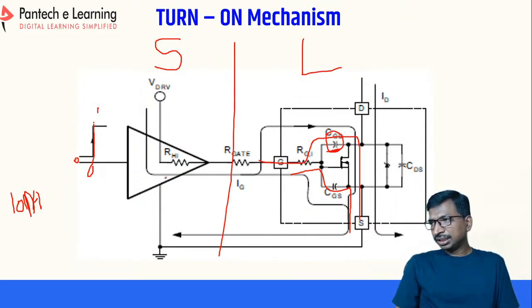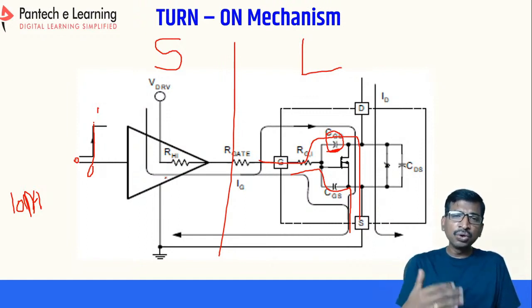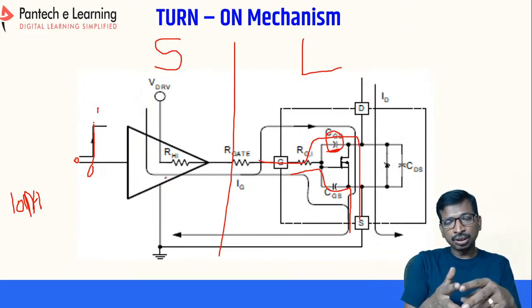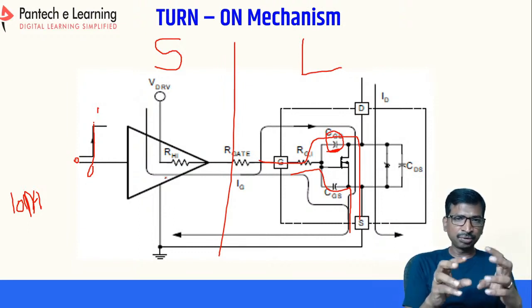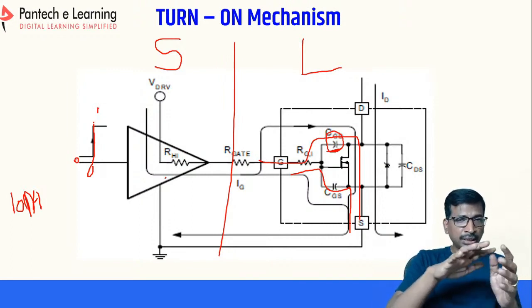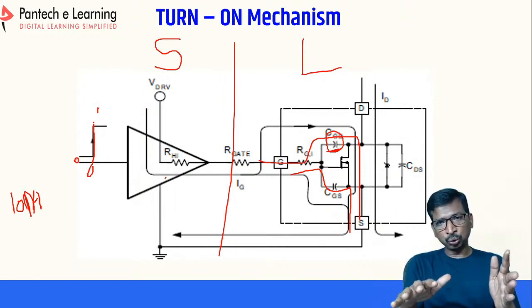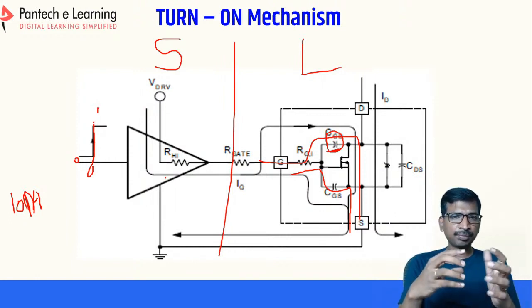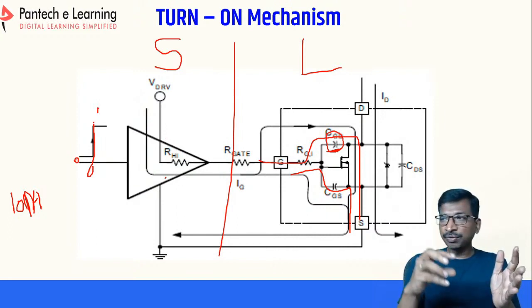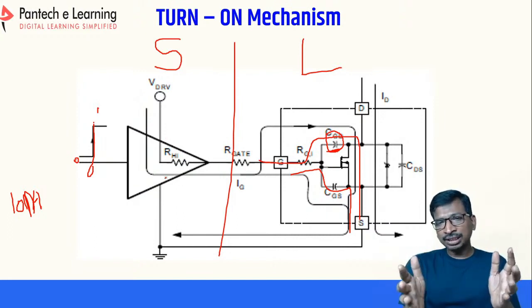What is the difference between shoot through and short circuit? Shoot through is where we manually generate the switching pulses so as to short circuit the same leg. To avoid that short circuit current, we introduce the LNC component to manage the shoot through logic. For the boost mechanisms, we introduce a short circuit. Short circuit, on the other hand, is a faulty mechanism.